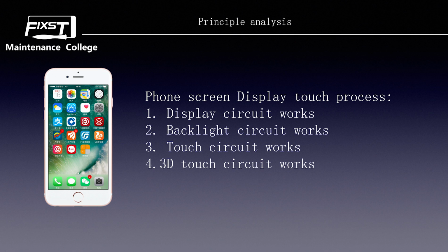If you cannot see the Apple logo when you turn on the phone and put it in a strong light place, it means that the display circuit has some problem. So at this time, we just focus our time on repairing the display circuit.